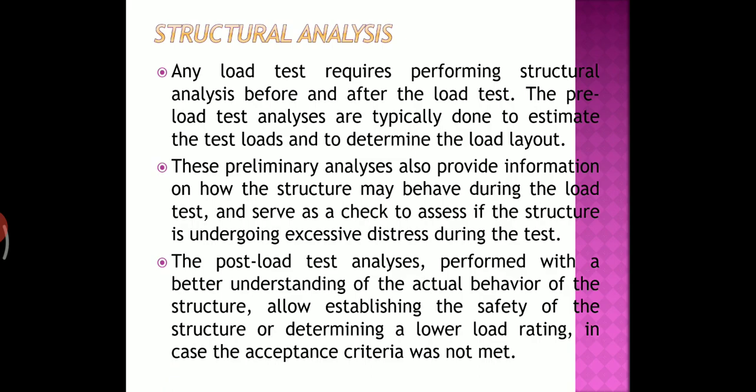These preliminary analyses also provide information on how the structure may behave during the load test and serve as a check to assess if the structure is undergoing excessive distress during the test. Then the post-load test analysis is performed with a better understanding of the actual behavior of the structure, which allows establishing the safety of the structure or determining a lower load rating in case the acceptance criteria were not met.